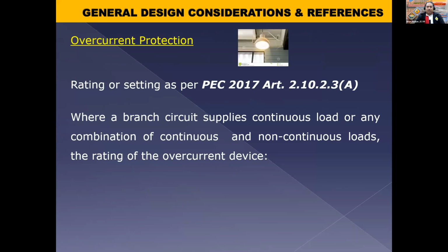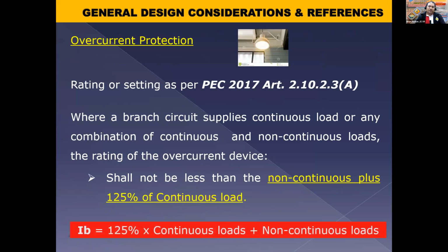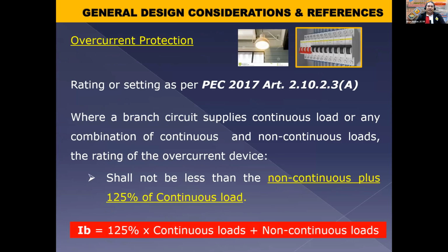So that's for conductor sizes. Then for overcurrent protection, it is straightforward. Whatever the rating of our computation for the conductors, we just match it with the breaker. We will have a question there later: if our computed load has no industry standard rating, what do we do, upsize or downsize? We will have a consideration for that later, and I'll discuss the treatment for that case.